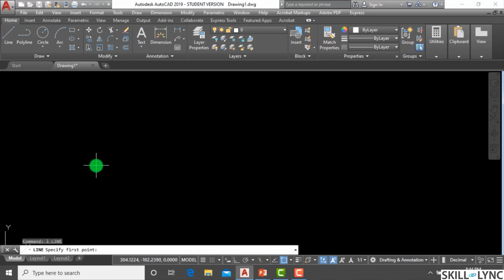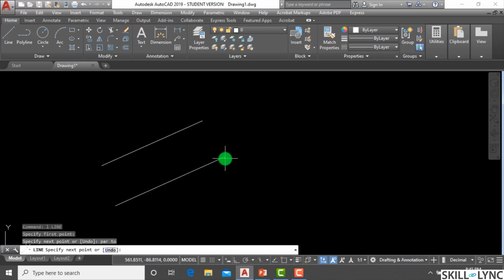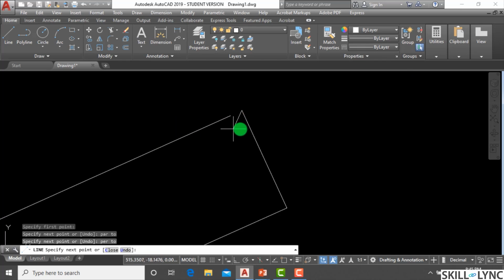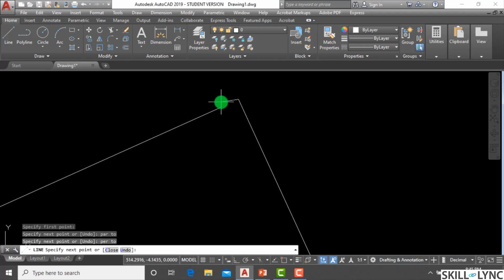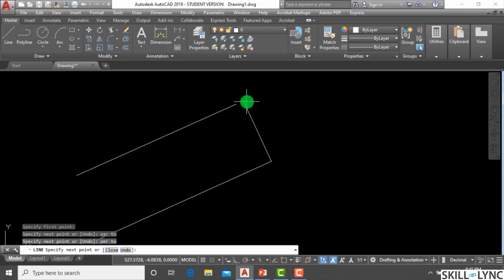So I have a line, and I put the object snapping off. I want to draw a line which is parallel to this, so I write PAR. Then you have this parallel over here. And if I want to draw a perpendicular to this line, I write PER, perpendicular, and bring it here. Now you can see that though the line is not intersecting, an apparent perpendicular is shown